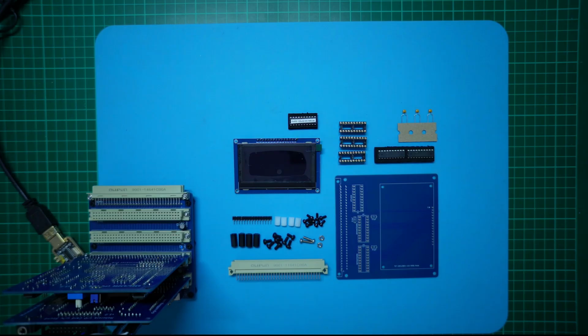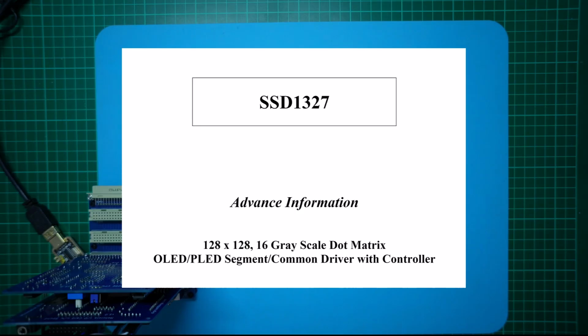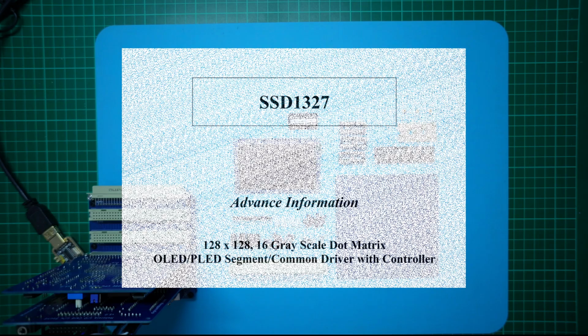It has also definitely occurred to me that this display card could even be used to create a self-contained Chip 8 based system as either the original 64 by 32 resolution or in a high resolution 128 by 64 Chip 8 recreation. Of course, it could also be used as a self-contained integrated display for displaying anything you like. The SSD 1327 controller that the display module uses also allows 16 shades of grey, that is 4 bits per pixel, so you're not just limited to on and off pixels.